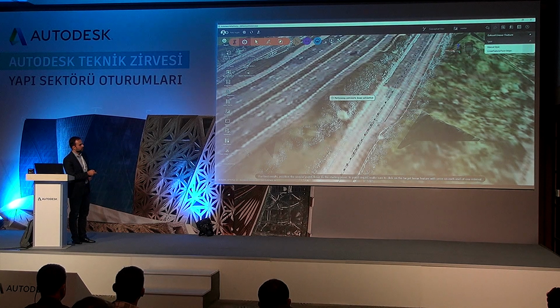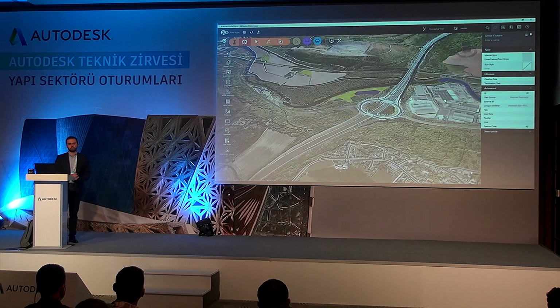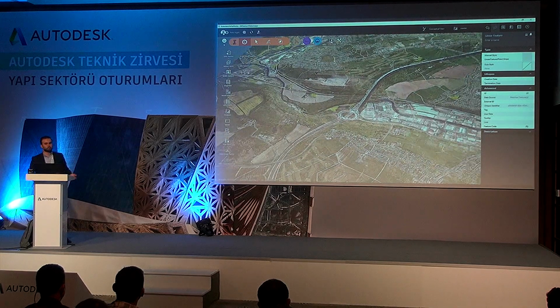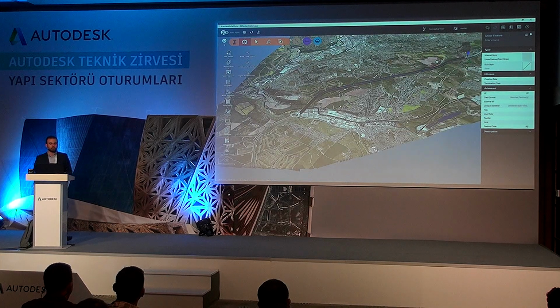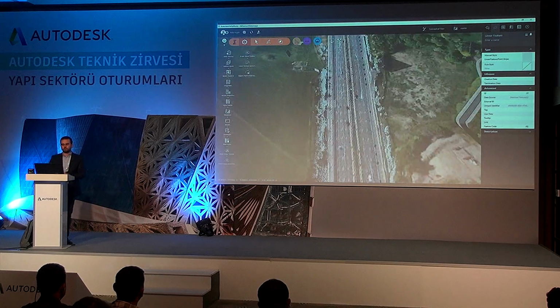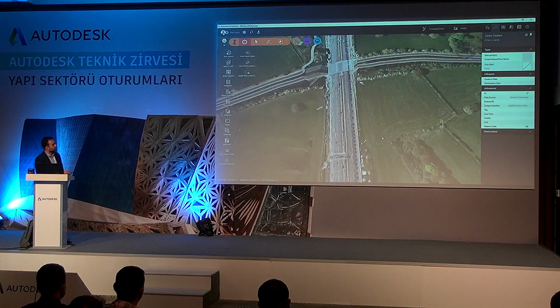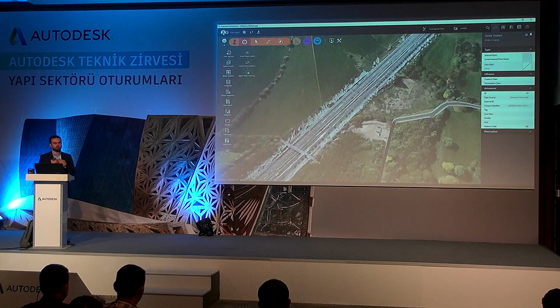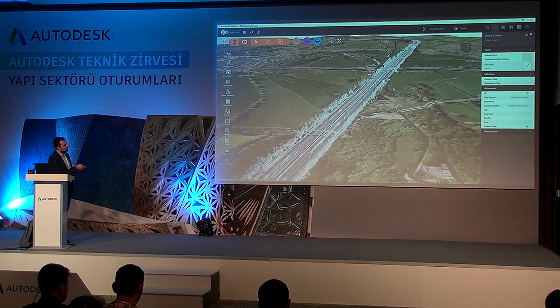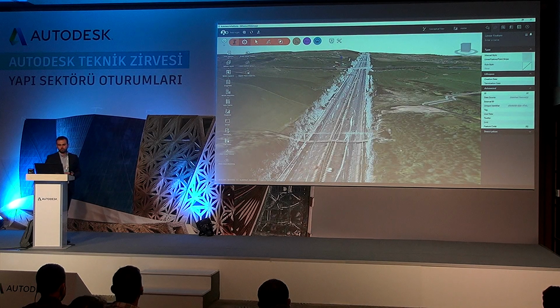We can do it for the center line, we can do it for the curb, we can do it for the road marking if we have any road marking in between, you name it. Just a few clicks and the software will automate the process. This is how mega infrastructure projects are being done nowadays. Point clouds into InfraWorks, generate the terrain, and then feature classes or feature layers. So as you can see, all the way. If I want, as a designer, to make a modification, I can go into one of the points and modify it sideways or even in terms of elevation.